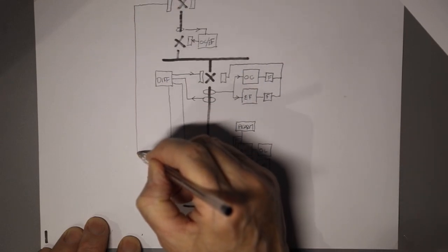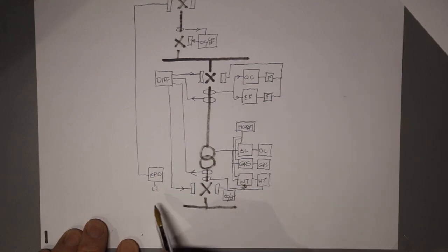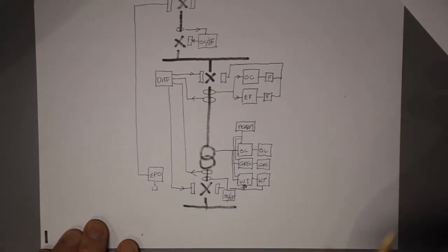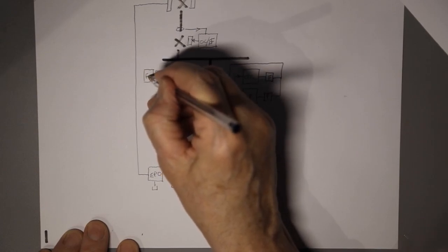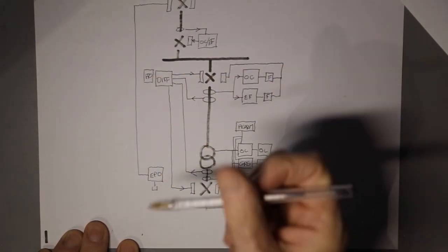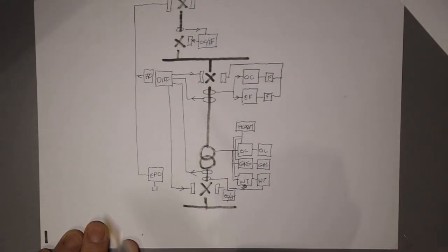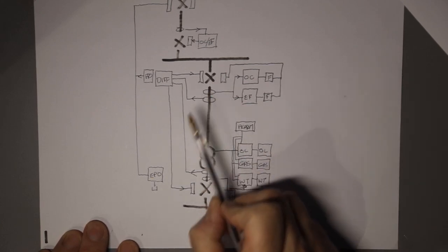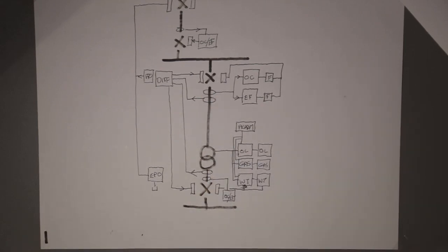Now what we typically want is an emergency push button to cut off all supplies to the unit. So here I've drawn it so that it operates the DNO circuit breaker. It might be that we have another EPO, because that distance could be quite big, and that EPO would operate again the DNO circuit breaker. But if this one was to only operate the upstream, then it would just hit the shunt trip coil on the main feeder.